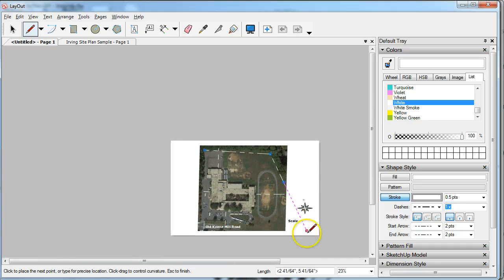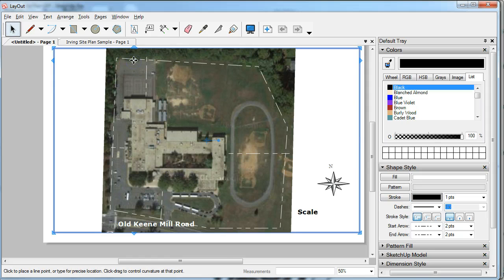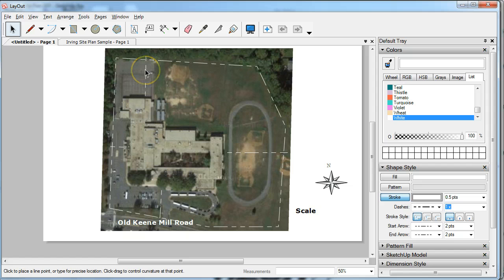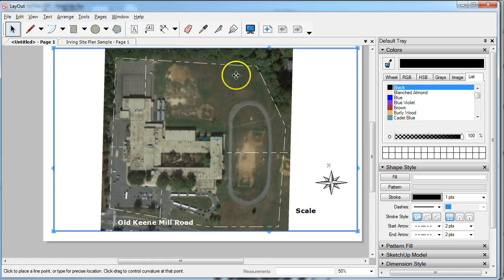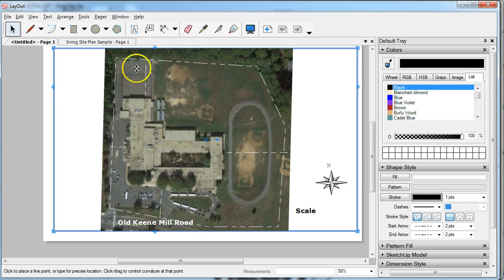Zoom out, come in a little bit closer here, and back over and connect. And there's your property lines too. So if I wanted to, I could highlight. Let's try this again. So to resize, I need to be very careful on what I click on. Sometimes you might select the whole site plan. Try to deselect that by clicking outside, and then click on the lines that you want to move. There we go. And I grab the handle and lower it so it now fits inside.